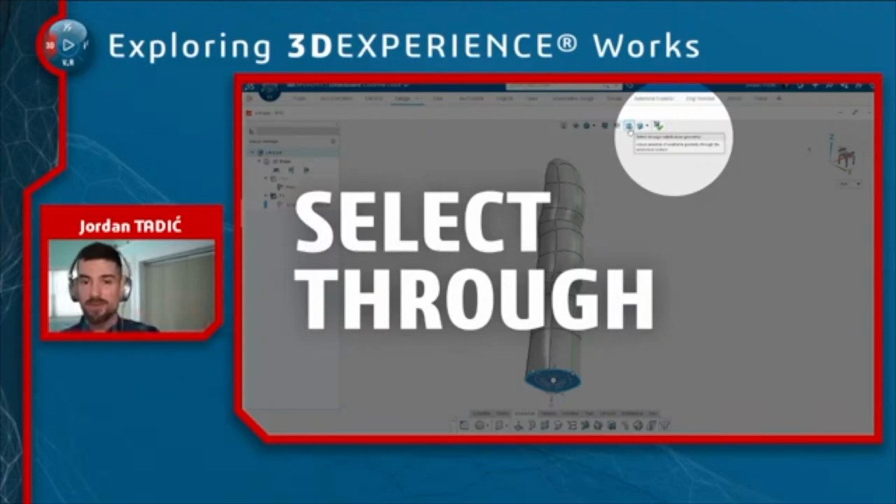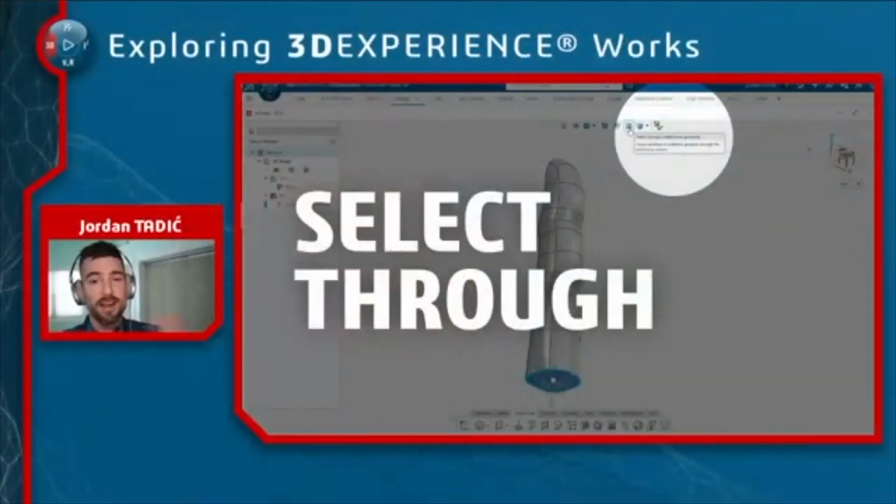Align by line, for one, is a way to ensure perfect tangency or curvature continuity across a mirror plane and no inflection points across a draft or parting line. You could do all kinds of things like that, but I'll show you a few more. In this case, I want the bottom surface to be perfectly aligned to the top plane. That's where it needs to be, exactly there.